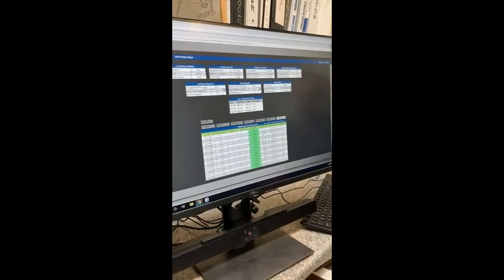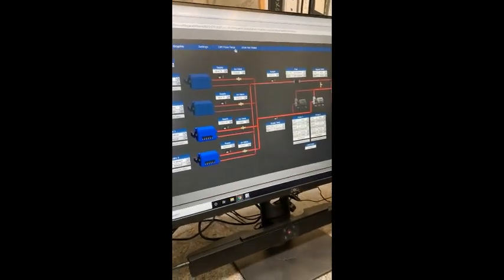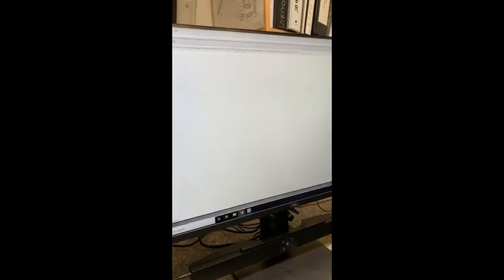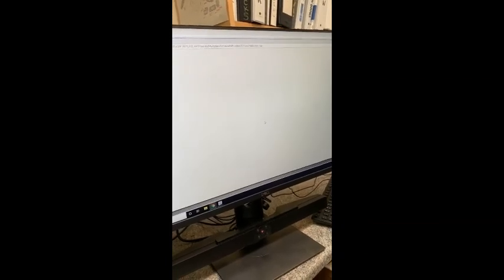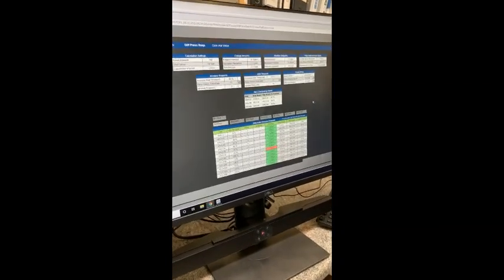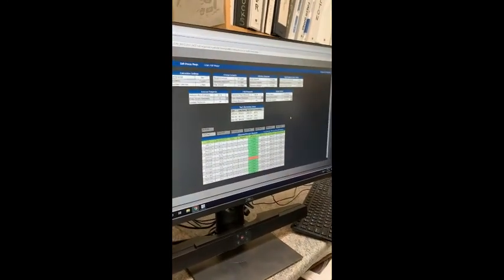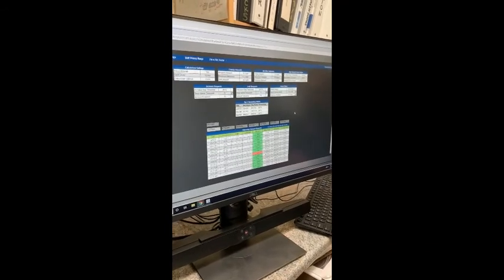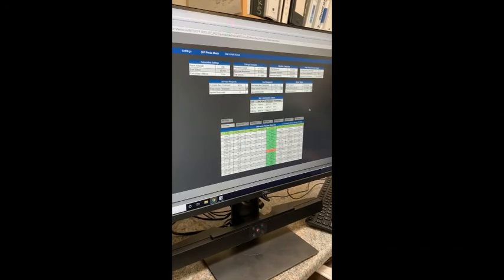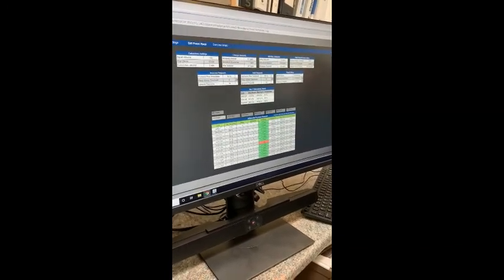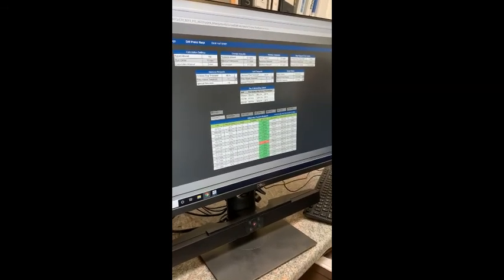Now if we looked at the hot water system, that'd probably be a different story. What we're trying to do is keep the worst case valve open between like 85 and 95%, so that the pumps have to work the least amount, with the least restriction, to get all the water everywhere it needs. So we can see this one right here is requesting an increase.